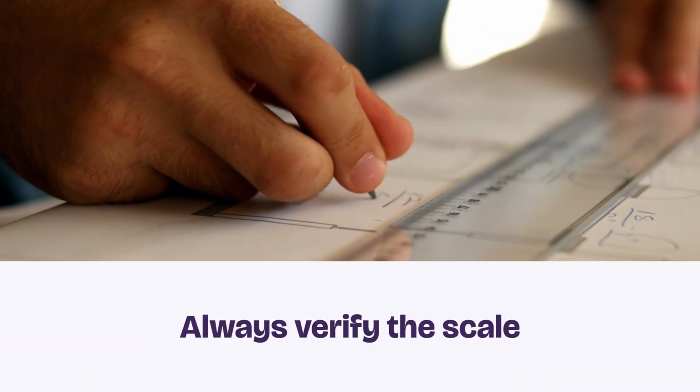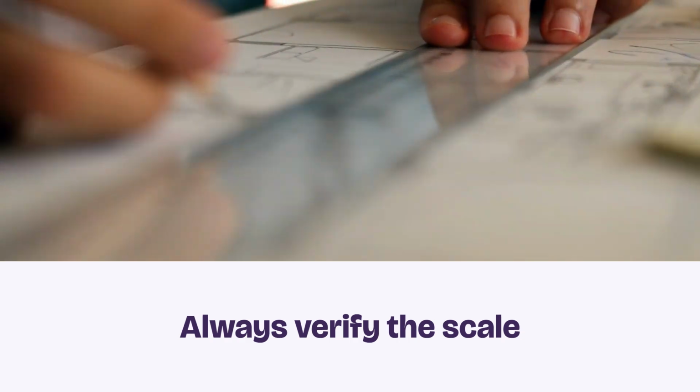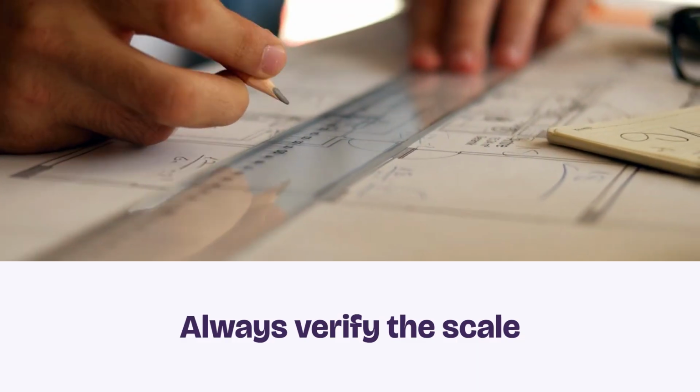Scale is critical. Plans are drawn smaller than the actual structure to fit on paper. A common scale is a 1/4 inch represents 1 foot. Always verify the scale before making measurements.